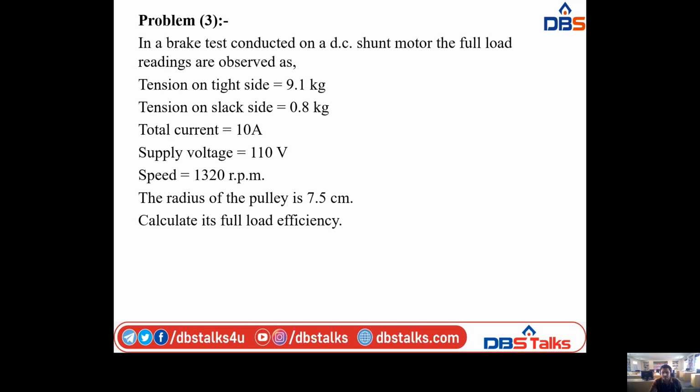So that is 647.27 plus 430.615, and motor output power is 7627.615 watts. So this is the input and output powers for the motor. And coming to the efficiency of the motor, you know the formula, eta is equal to output power by input power into 100. So here the output power of the motor is 7627.615 divided by input power is 8705.5 watts into 100. That is equal to 87.61% for the motor efficiency.